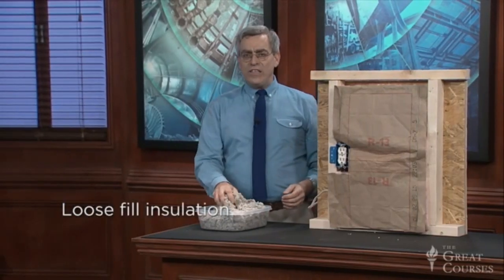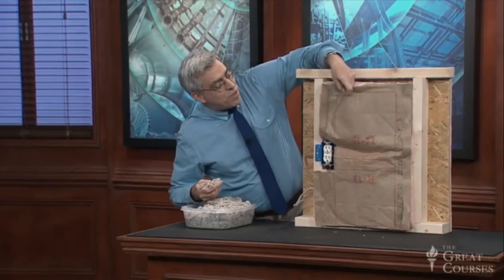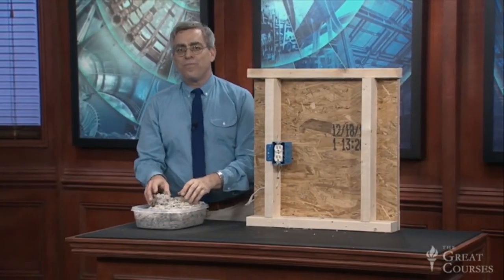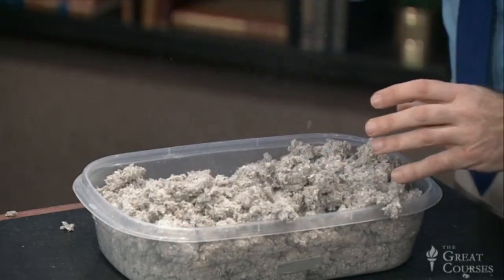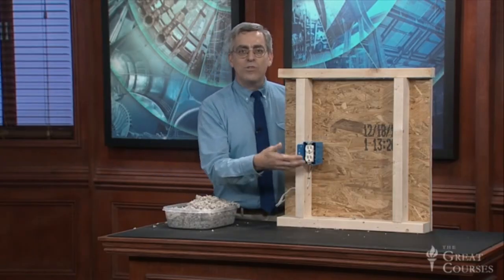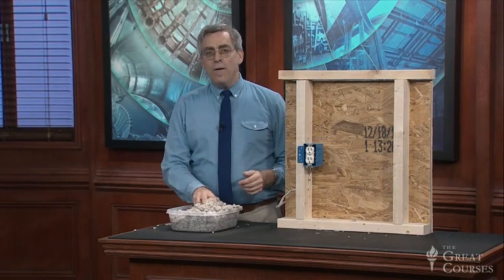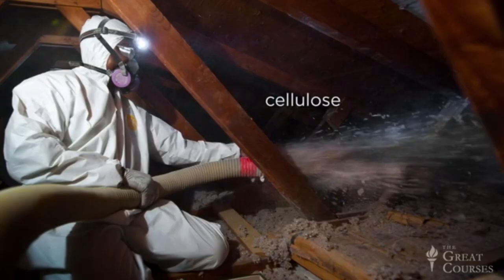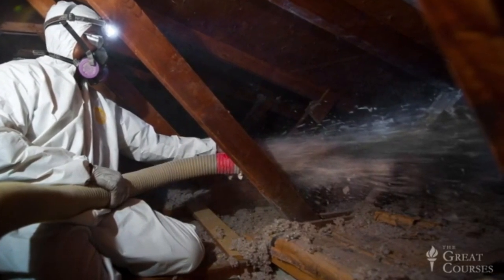This is loose fill insulation. It's typically installed by pouring or blowing the material into the cavity wall between studs and joists. Now, I can't demonstrate this without having the sheetrock installed, but I think you can see that because of its loose consistency, it's very effective at filling the spaces around pipes and wires and electrical boxes without any special fitting or trimming. And by the way, this particular loose fill insulation is cellulose. It's actually made from recycled newspapers, and it has an R value comparable to that of fiberglass.